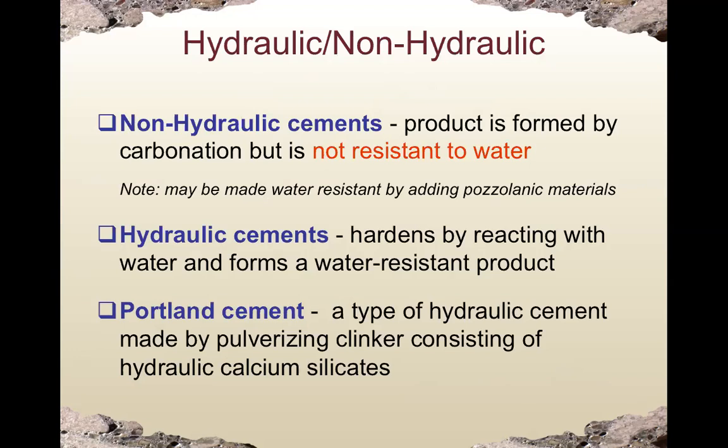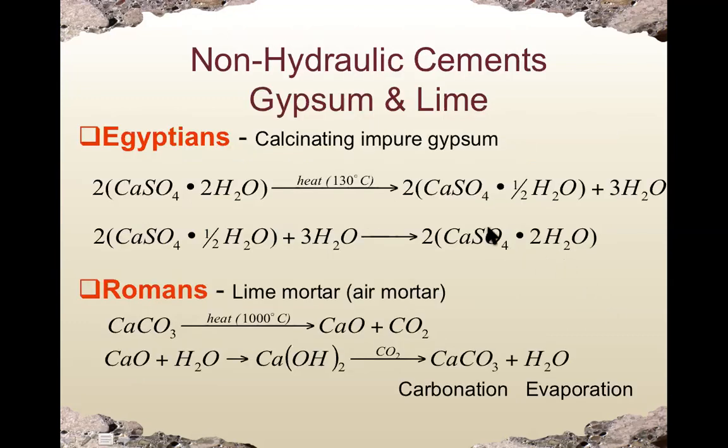The so-called non-hydraulic cement, including what we just discussed, the product is formed by carbonation, but the final product is not resistant to water. Okay. Why do we say that? Let me show you the chemical reaction. For example, the gypsum can be dissolved into water. Limestone seems to resist water, but actually it is not.